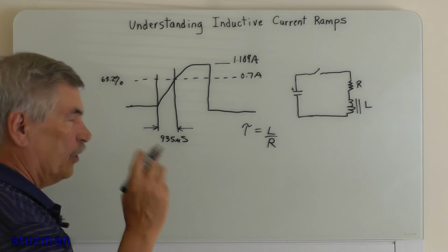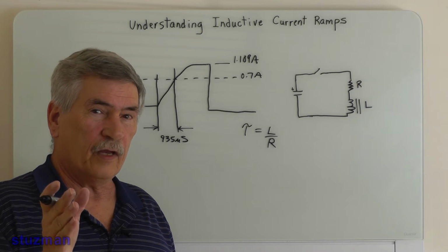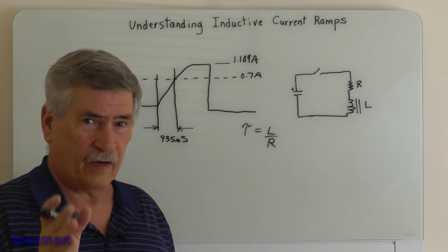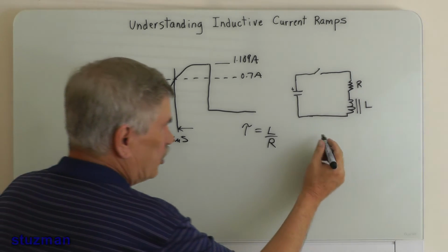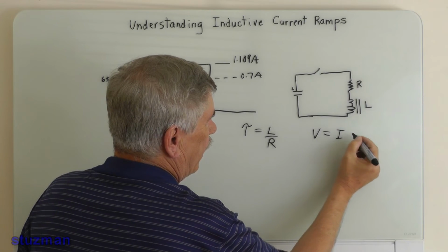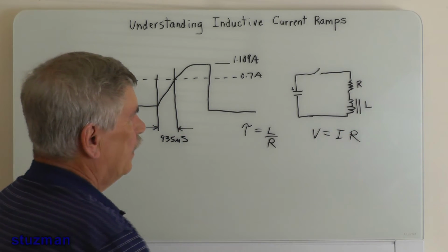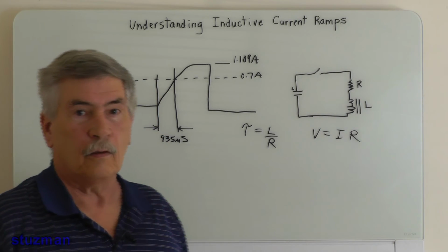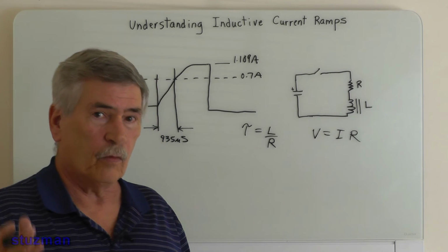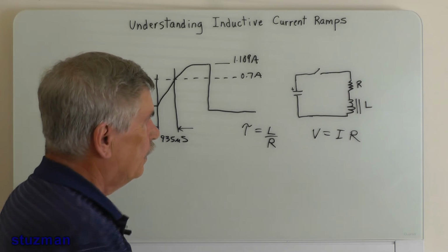But do you remember we looked up at our supply volts, and we saw that it was 14.75 volts, right? So let's step over here to the side, and we're going to see that V is equal to I times R, right? Now, we want to find what? Well, we need resistance. We want to know what is the resistance of the windings on that fuel injector.